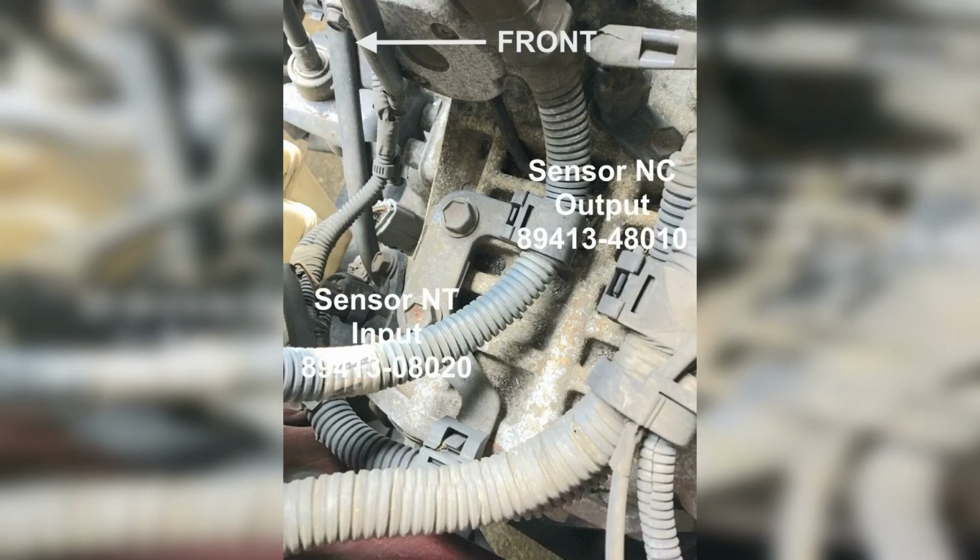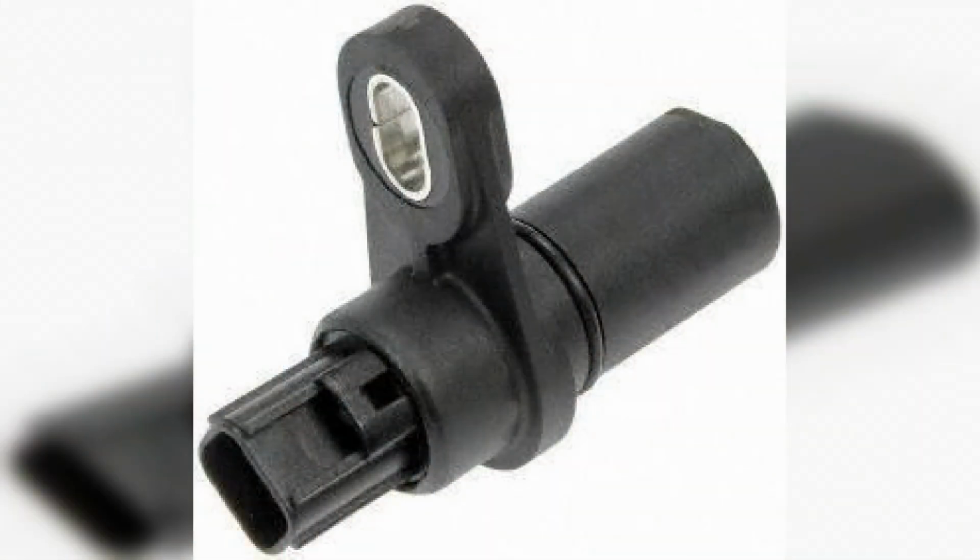So, in these articles, we refer to the ECM or PCM when discussing the main onboard computer, but an increasing number of vehicles have separate engine and transmission control modules that communicate with each other via the CAN bus. As a result, you may have an ECM and a TCM, but the ECM may display TCM-related codes, such as this one. Note that the definition of code P0717 may differ depending on the vehicle manufacturer. Consult the appropriate repair manual or repair database for the exact code definition.